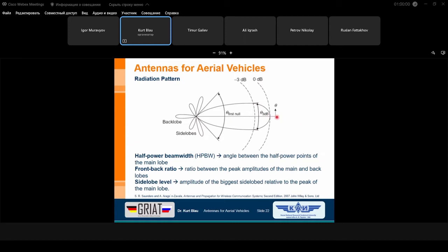Here we can measure the full power, and the angle between the half power points, the 3 dB points, exactly minus 3 dB. If this is the maximum, related to itself, maximum divided by maximum, normalized to the maximum, the value is 1 here. In log scale it's 0, and then if you go down to the half, we have minus 3 dB.